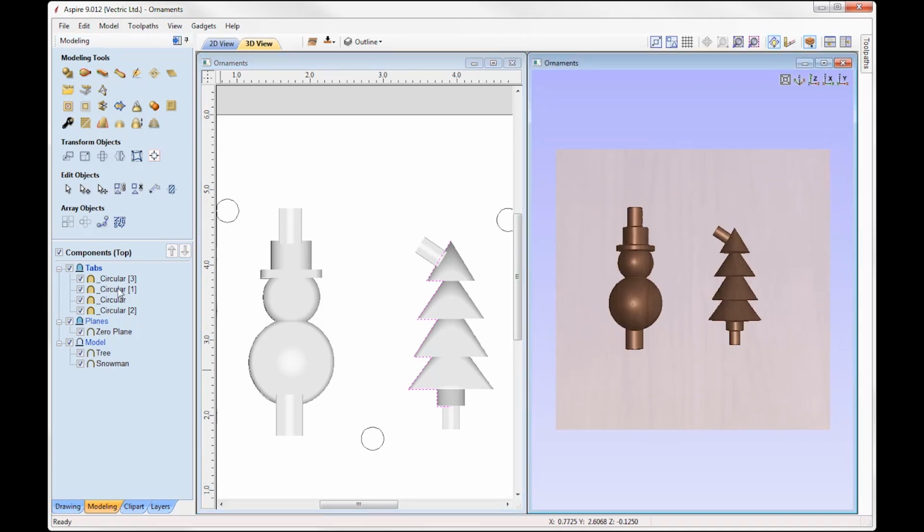Okay, you can see in our modelling tab, I have a plane level here. So we've got a 0 plane in here that has a negative height of 1/8 of an inch, and that's just to ensure that when we come to machine the top side, our tool drops below 0 to eliminate what could be a cusping effect around the seam of the model. So we're just bringing that down a little bit so we don't have that cusping.